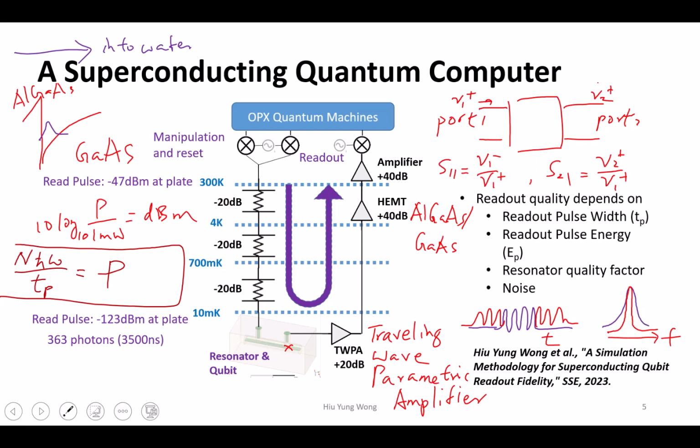So both have an effect in helping you distinguish whether it is 0 or 1. Superconducting resonators have very high Q, but Q cannot be infinity. We are talking about some very small number here. Look at the photon, there's always a limit. You cannot just say that you don't care about the Q, because it's not infinity. How much frequency shift are we talking about? Let's take a look later.